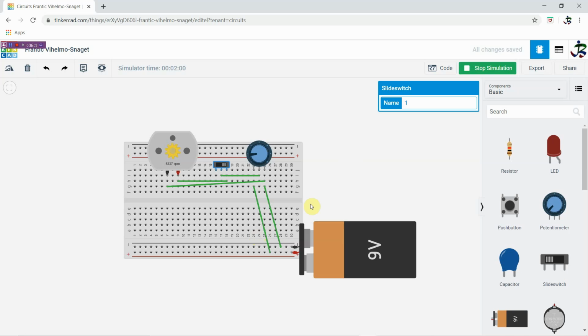You have to make the control of the two motors with a single slider switch and two potentiometers. As you switch on the slide switch, both motors should be controlled, and then with the help of the two potentiometers you should be able to control each motor's speed. Right now you are controlling a single motor; you have to control two motors' speed with the help of two potentiometers. So the same circuit you have to make twice. Do the project by yourself and then show it to me, and after that you will move ahead. So pause this video, go for the practicals and then come back.